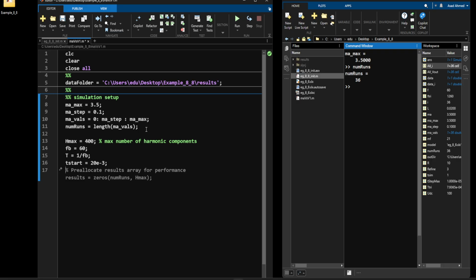You will have to figure out from the simulation results when the results are already stabilized, and then specify a particular range of time there. And t end should be a period, that means t start plus T, one period. This Fourier series is a period signal-based analysis.